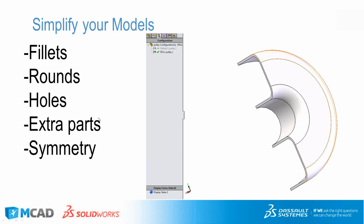Like if you had a large long beam and there was just a small little hole right in the middle, like it's 2 feet long, and there's a 1/16 of an inch hole somewhere in the middle. Well, it's going to break its back trying to mesh that little hole, and you don't need it. It's not important to the sim unless you are actually working with that one little 1/16 inch hole. Other than that, you don't really need it there.